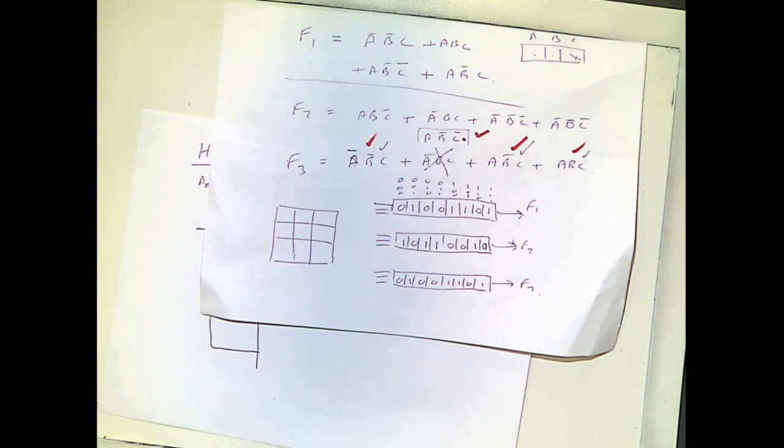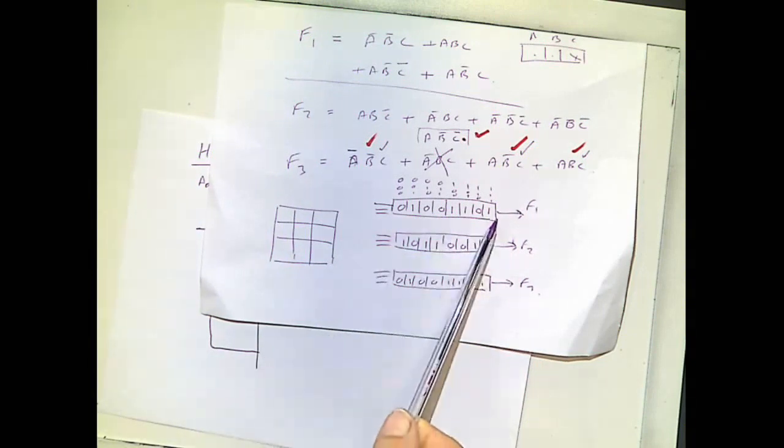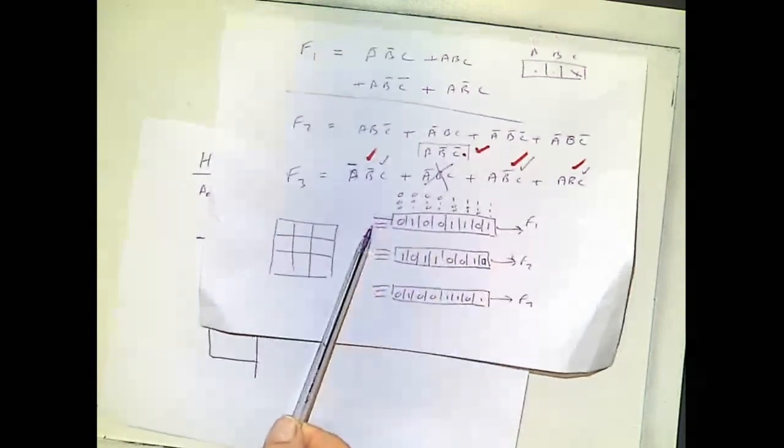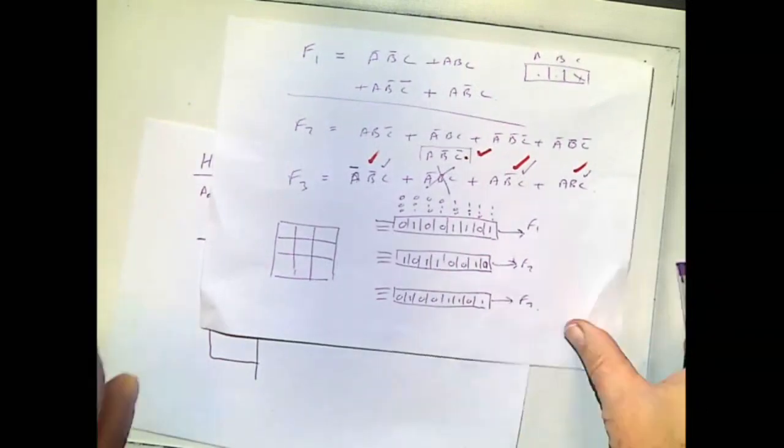We've got a megabit to address. What is a megabit in number terms? 1 million, 2 to the 20. We have 2 to the 20 locations to address. How many bits in the address field? 20. In this case, 8 bits, 2 to the 3, 3 address lines. 16 bits, 2 to the 4, 4 address lines. We will have 20 address lines.